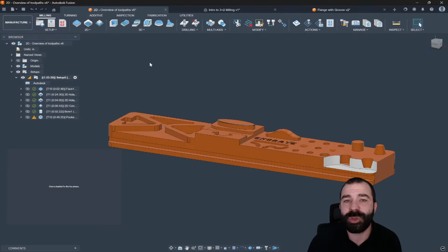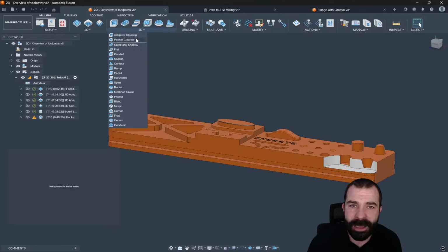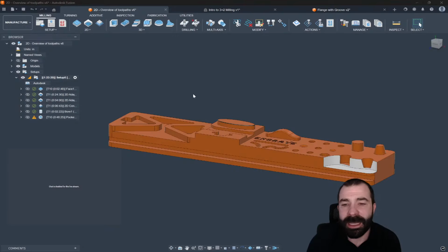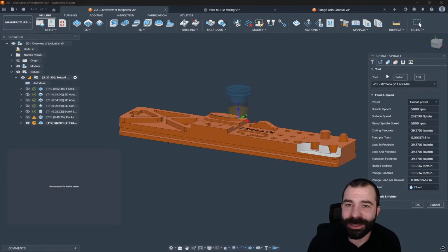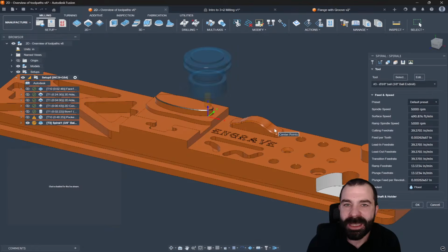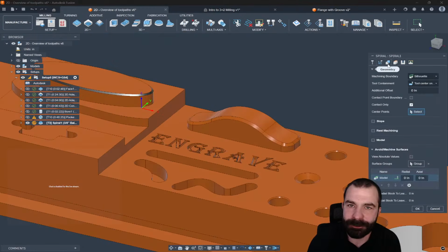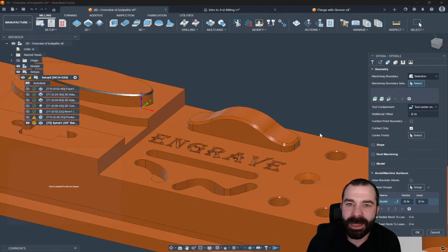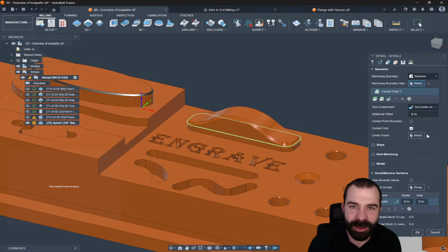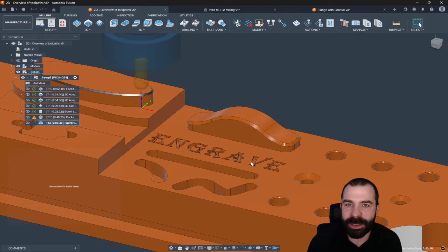If we switch to a little more of a 3D toolpath, again, I keep referencing last week's video because it will make all the difference in the world for a lot of you new to Fusion. If I was to want to 3D this kind of feature on this part, and I go through and I say a selected boundary, and with that, we're going to go ahead and stop with our tool center on boundary. I just want to get a toolpath to show you.